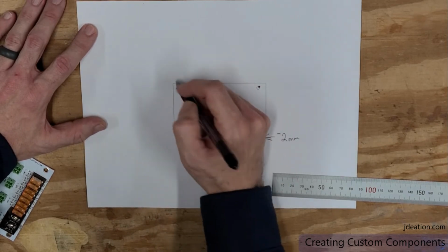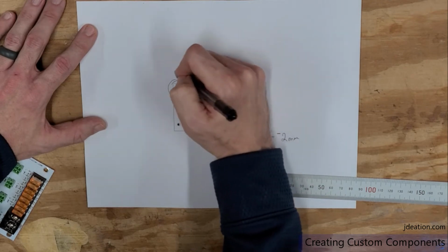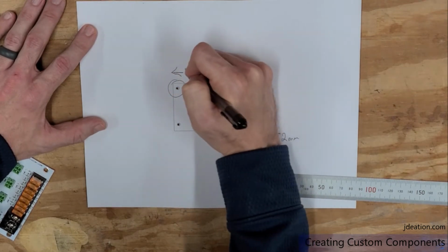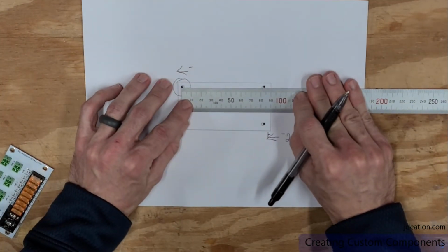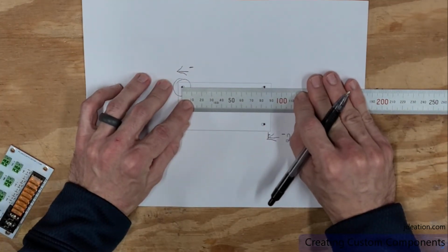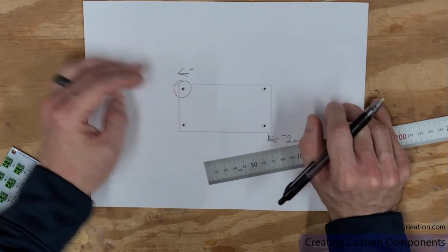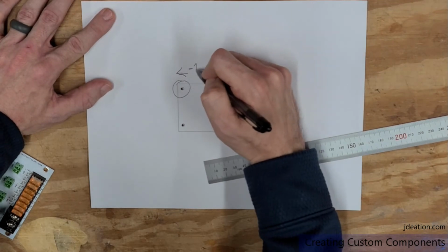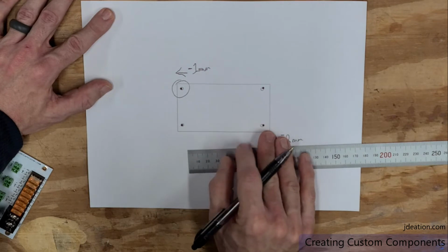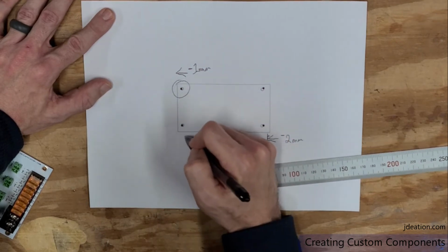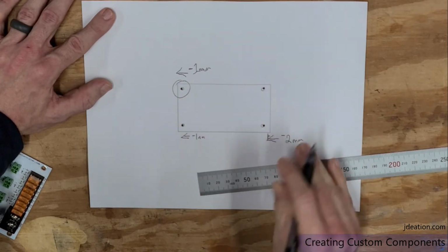But you know what? This one definitely, I think, let's go ahead and move that hole a little bit to the left. So we're going to subtract a tiny bit. Let's see, not much from the center of that black dot to the center of the hole. Let's say 1 millimeter. We're going to subtract 1 millimeter. And then down here, it's not much, but let's just assume that the holes on this board line up. So let's just go ahead and subtract 1 millimeter from here as well.